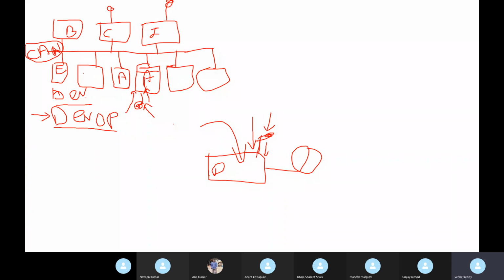Diagnostics is another functionality. Now I'll come to another functionality called the power module, because every ECU needs power supply. Generally the battery gives the power supply, like 12 volts or 13 volts, plus or minus 3. This is in the car, but in our lab we will give a regulated power supply.